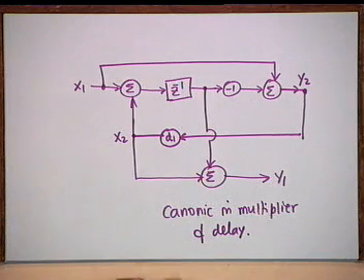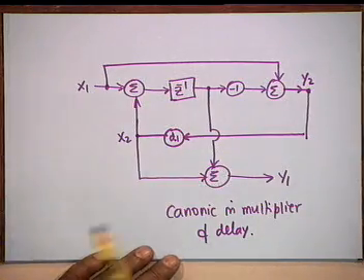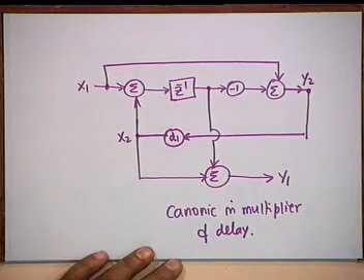All right. This is a very beautiful first order structure, first derived by Mitra following his concept of digital two pair. Normally it would not occur to one that one can draw such a structure. The transpose of it, which is the choice D, B and D are transposes of each other, is equally applicable. And you see, the virtue of this is that even if D1 changes, it can change due to various reasons, the all pass property is maintained. Okay. Magnitude shall still remain 1, the phase shall deviate, the delay shall deviate, but only to a reasonable extent. There will be no magnitude distortion.